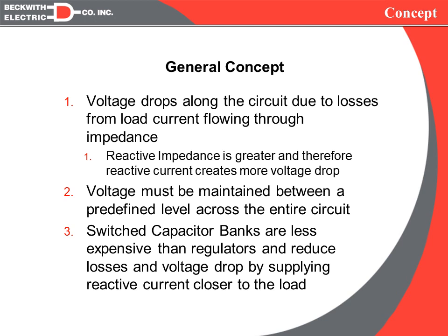And as a last concept, switched capacitor banks are typically less expensive to install and also for long-term maintenance than our line regulators. And they have the added advantage, besides regulating the voltage, of also being able to supply reactive current closer to the load, so that reactive current doesn't have to flow through as much of the impedance, and therefore we won't see as much voltage drop.